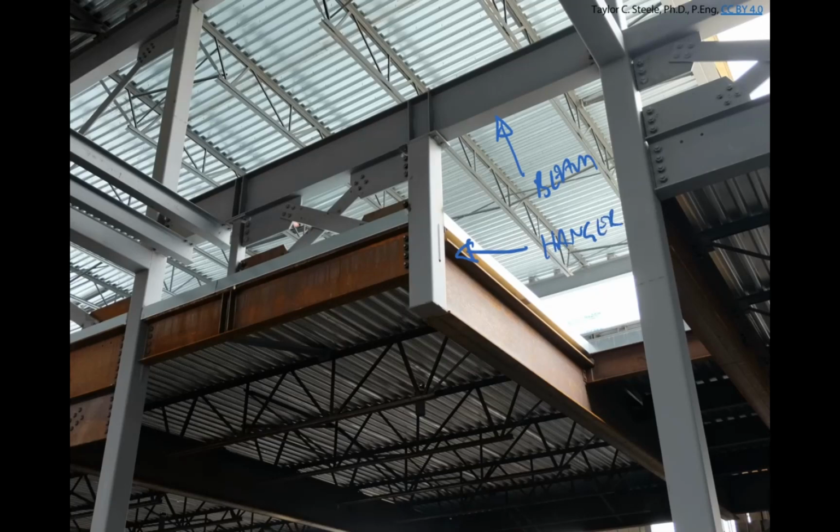It hangs the floor from this beam above so that all the load that comes in through the joist and girder elements that are framing into that develop tension in this hanger. And so that element's going to be carrying a tension force that comes from the gravity loads acting on that floor area to transfer that up to the beam to support the floor at that corner.